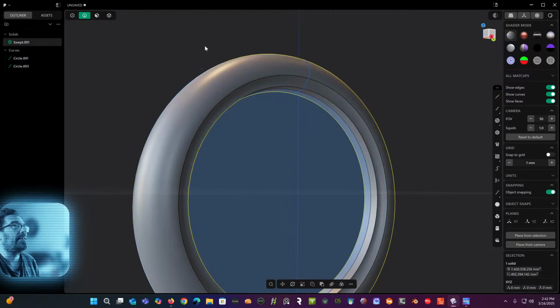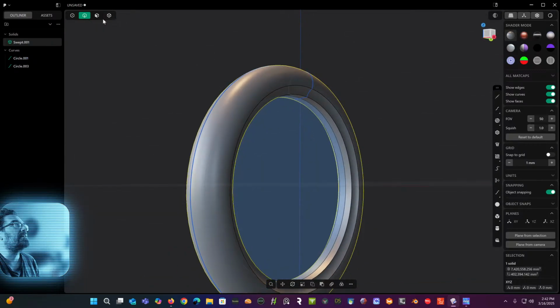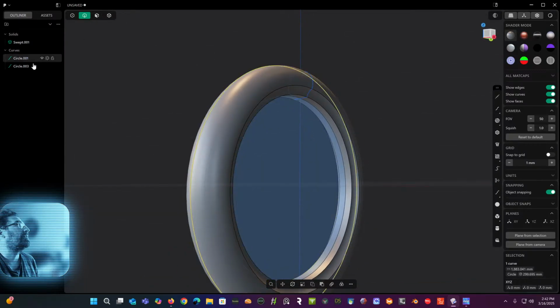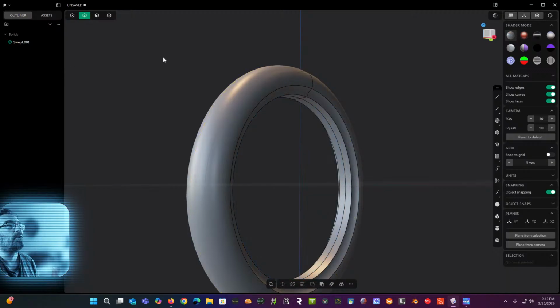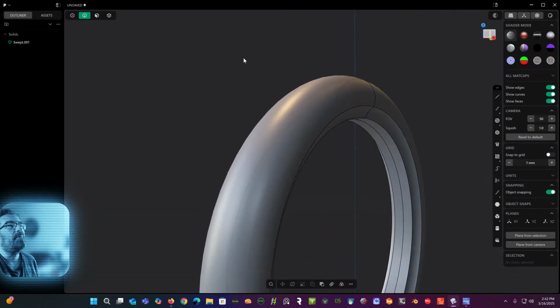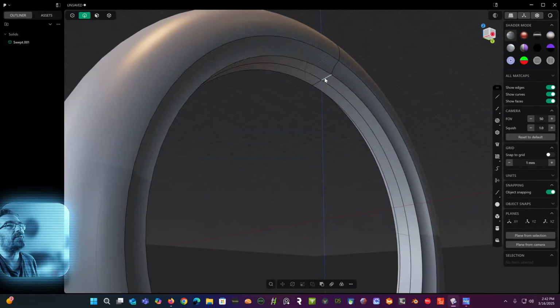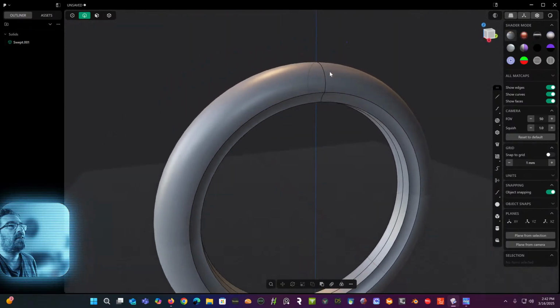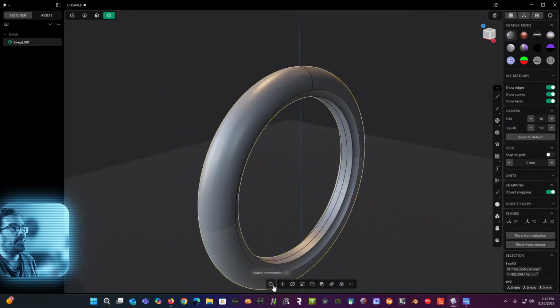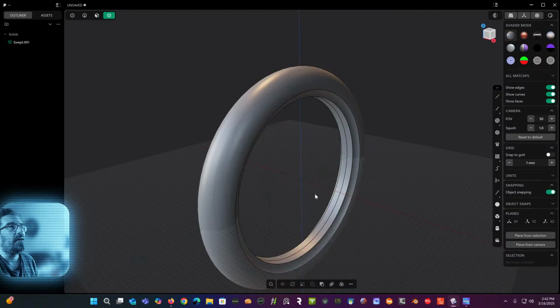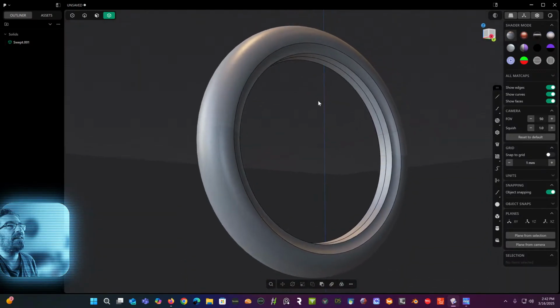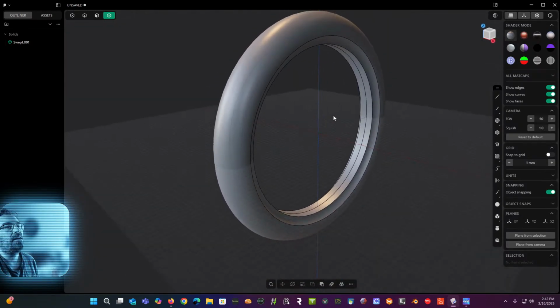We're going to say, okay, now we've got that kind of classic tire shape that we were sort of there and we sort of weren't. So there we go. I mean, if we wanted to, you could always hollow this or take out these faces or whatever you want. Not necessary here. And also just to kind of fix this up, I'm going to take it and delete any redundant topology so we don't have any extra lines that we don't need either.